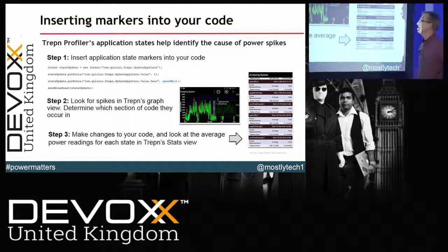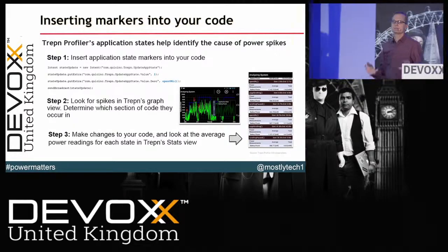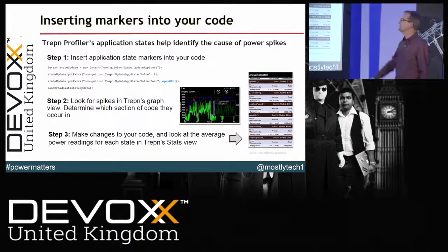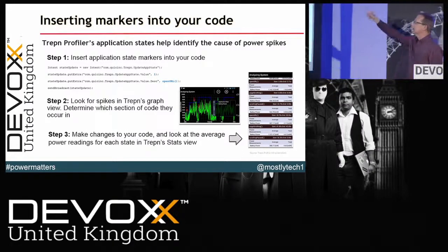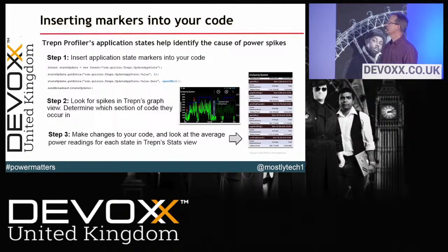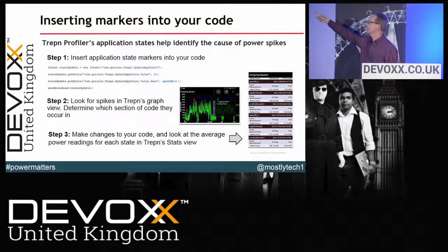Sometimes the raw power is almost kind of random looking, so it's helpful to look at a statistical view of the averages. You can see the first intent here is loading a web page. It shows that it's drawing 1100 milliwatts. Then we scroll the page. Then we pause scrolling. You can see a significant drop in power.